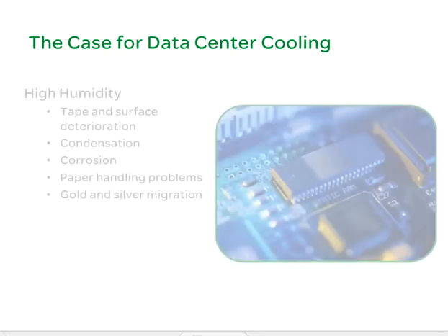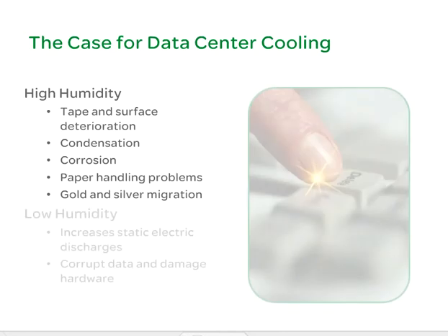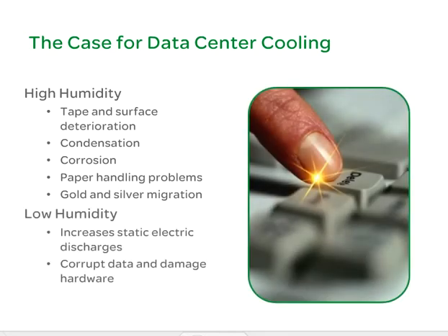High humidity can result in tape and surface deterioration, condensation, corrosion, paper handling problems, and gold and silver migration leading to component and board failure. Low humidity increases the possibility of static electric discharges. Such static discharges can corrupt data and damage hardware.